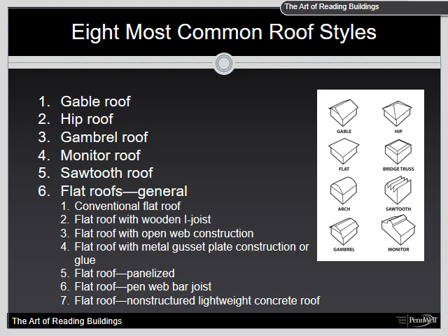Valley rafters are used where two roof lines are joined. Jack and common rafters complete the structural members. The ridgepole and rafters are typically 2x6-inch or larger, with rafters 16-inch to 24-inch on center. Rough sawn 2x3-inch or 2x4-inch rafters, 36-inch on center, were also used in the older wood frame structures.